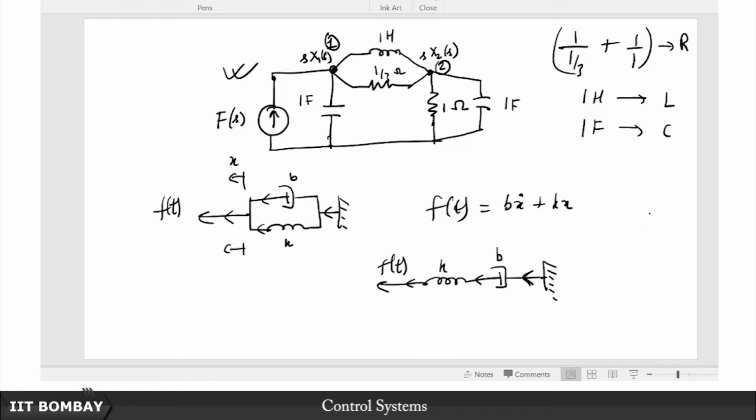It is exactly like when you solve problems on lossless pulleys, where you had this tension here and this tension here, so the same tension on either side of the pulley. So tension is nothing but a force. So force happens to be the perfect analog of a through variable, which is a current, which is another reason why we are so fond of this parallel analog, because it helps restore the physical correspondence between these two. Now let us see what happens in this case.